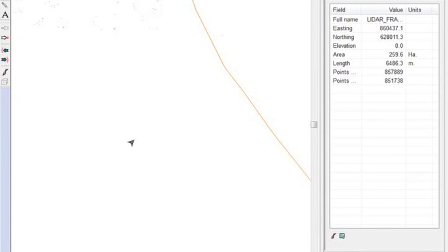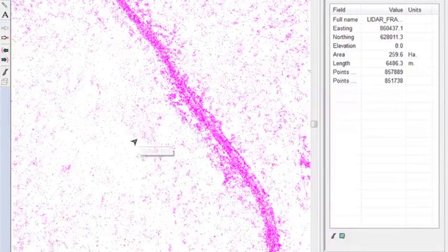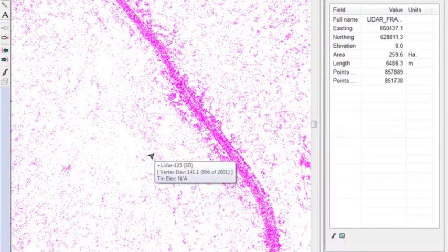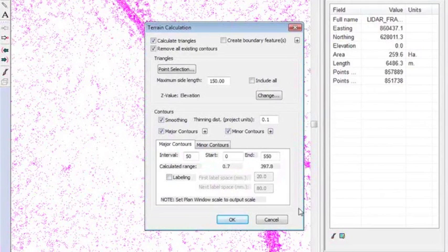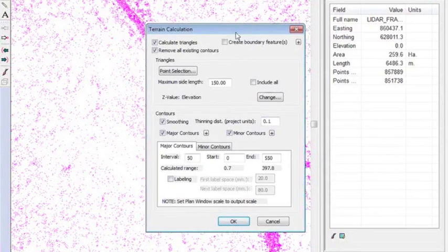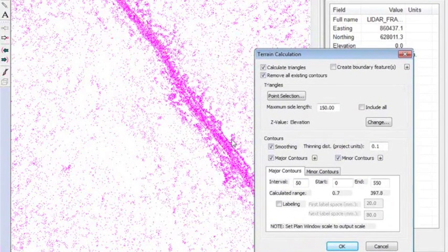So people may tell you that you're getting LiDAR data that's 1 point per meter squared. Depends on the foliage. And watch out, because sometimes you're going to get a LiDAR file from a provider that actually looks like a grid. The points are sitting on 1 meter even spacing. What they've done is they've made a surface, which I can do here very quickly, and they've just laid a grid over top of it and sampled the surface. So you lose the information that I can see here, which is where are the points dense and where are the points not so dense? Where am I missing data?